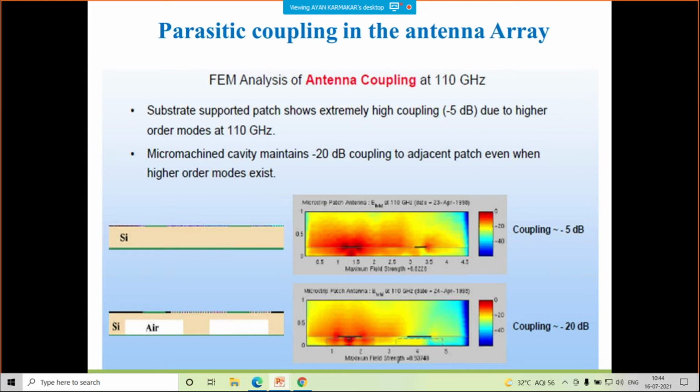And coming to antenna array problems, a single antenna cannot always serve your purpose. If you want much more gain and much more directivity, you obviously have to go to an antenna array. But the problems of an array are, first, feeding, and second, mutual coupling. This mutual coupling can sometimes be cross coupling, and it may be a negative coupling. From one antenna to another it may hamper, like a negative interference, so that your whole radiation pattern and your whole gain will be diminished instead of increased.